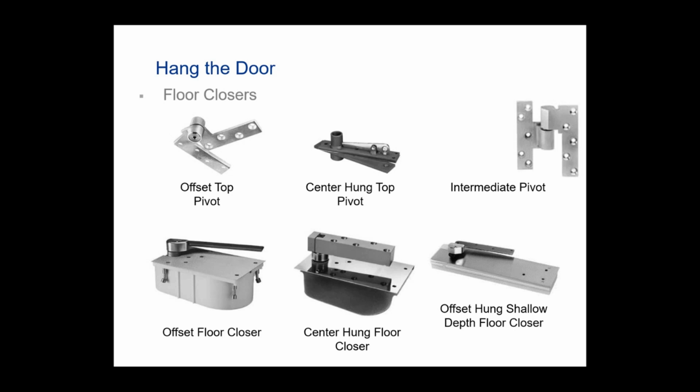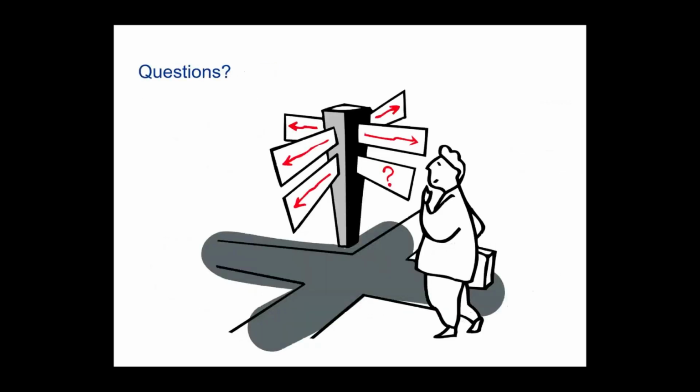A lot of aluminum storefront manufacturers and distributors have started to move more towards continuous hinges for ease of installation. You don't have to go through that planning, and it's a little bit easier for an end user when trying to fix one after 20 years of use, 30 years of use, 10 years of use, or even 5 years of use sometimes. So just make sure that you identify that prior to building your building.